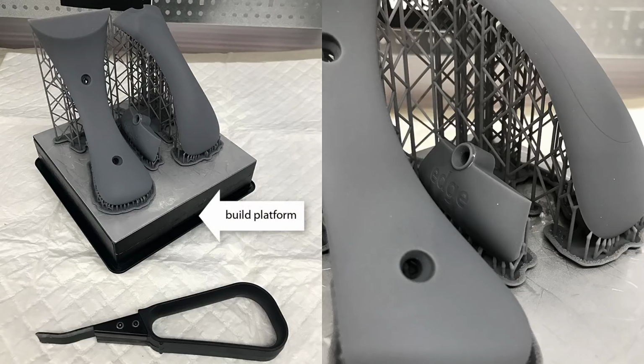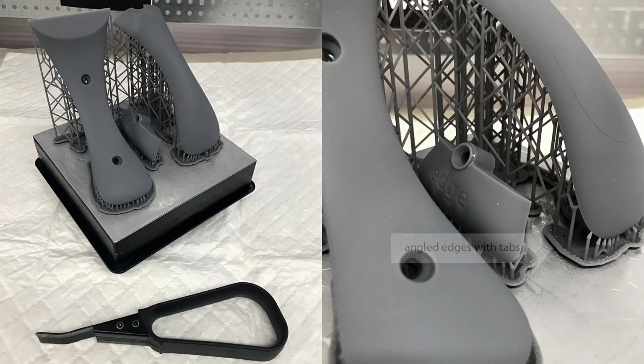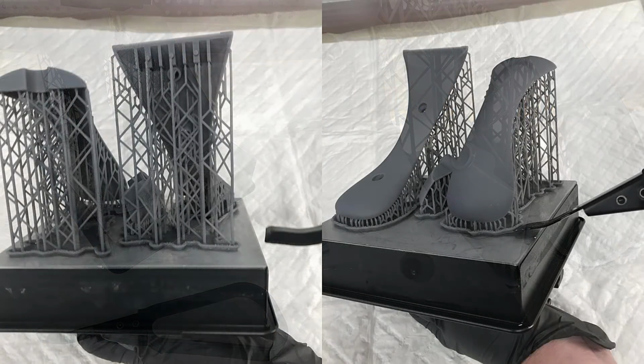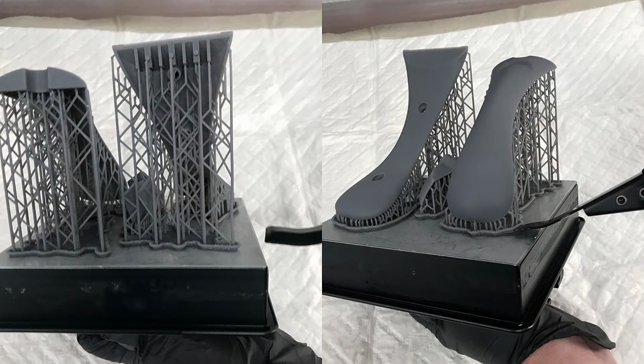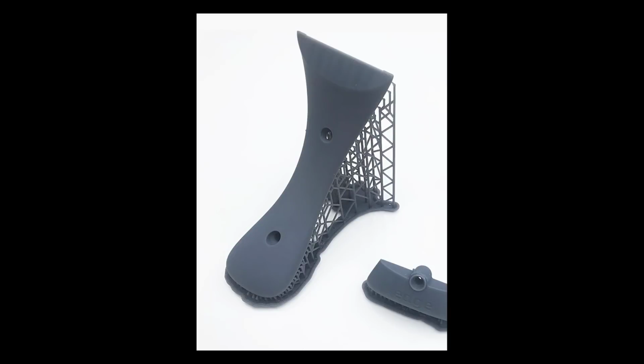When PreForm calculates the supports, it also creates a base around the scaffolding. This base has angled edges and quick release tabs that are automatically designed and built. These angled edges and quick release tabs make for an easy removal of the parts from the build platform. At this stage, the base and the scaffolding are still connected to the parts, and the next step would be to cure the parts. This stage is optional for standard resins, but essential for engineering resins.